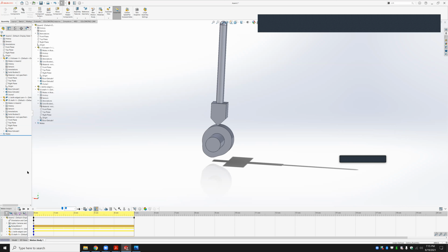And it's trying to do a tangent mate. And for some reason, we don't have the option to do a coincident mate. That means that something's constraining. So since that's the case, it's not going to. Oh, unless it lets you do it. What happens if you stop? Can you show me what mates you currently have? Oh, yeah, I think I need to delete a couple of these.